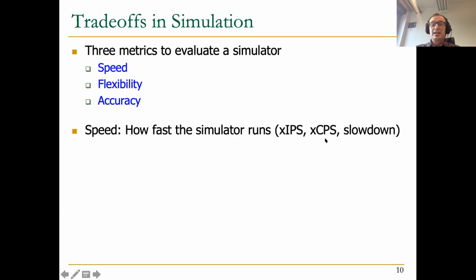Basically, you model how the underlying hardware behaves, what the latencies are. If your cache takes 5 cycles, 7 cycles, 8 cycles, 10 cycles, you model that. And as a result, you get a metric of performance of what you would expect if you actually design your idea in a system that you imagine, right? But that's microarchitectural simulation that gives you performance and energy numbers.